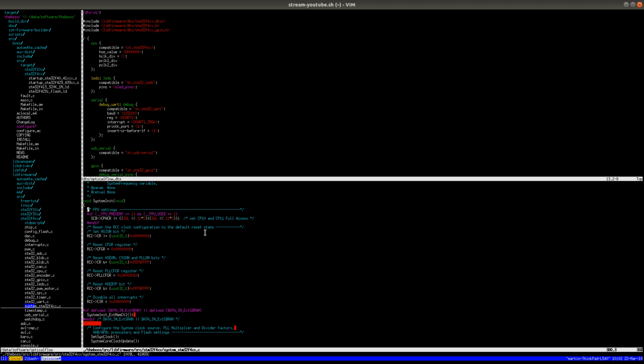Like if you don't do this, I think you get a hard fault, or you get some coprocessor related fault the moment that your code does some instruction that uses the FPU. And by the way, the printf code seems to execute some of that instruction. So if you don't properly initialize the FPU, you get a very weird fault when you call printf, and it's counterintuitive to figure out exactly what's going on, because you may not be even using any floating point in your code, but the moment you call printf, it actually just fails. And having this line is important.